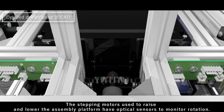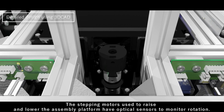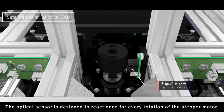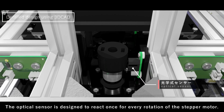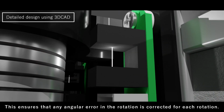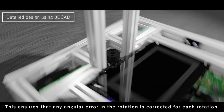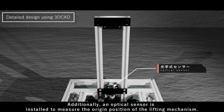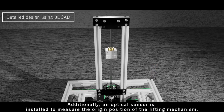The stepping motors used to raise and lower the assembly platform have optical sensors to monitor rotation. The optical sensor is designed to react once for every rotation of the stepper motor. This ensures that any angular error in the rotation is corrected for each rotation. Additionally, an optical sensor is installed to measure the origin position of the lifting mechanism.